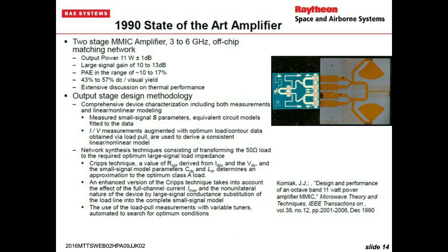Okay, that sounds great. We have another question here. What is the reason to use a cascode topology for designing HBT-based PAs? Well, the basic thing is it gives you the gain performance of a 1.5 stage amplifier and the size of a 1 stage amplifier.